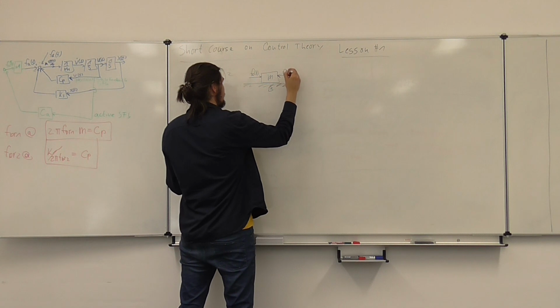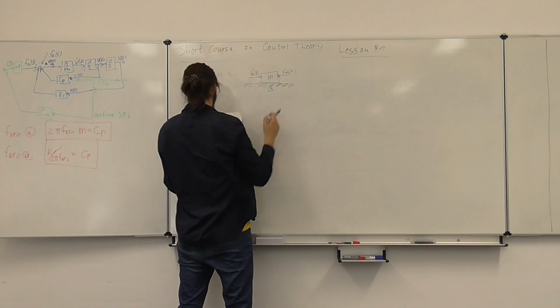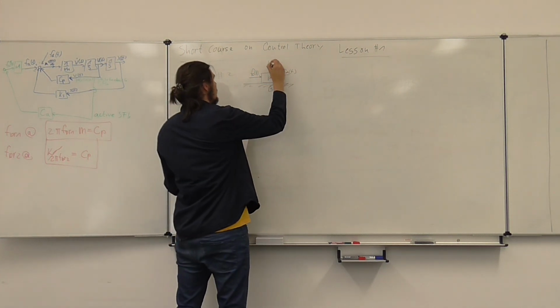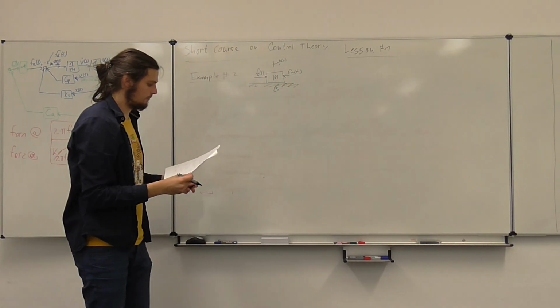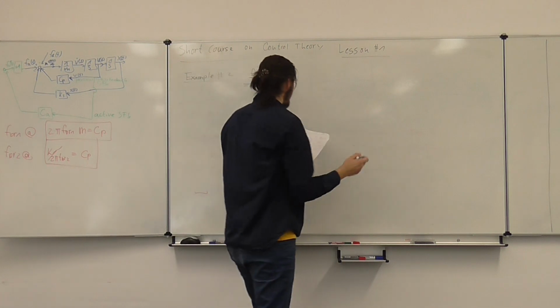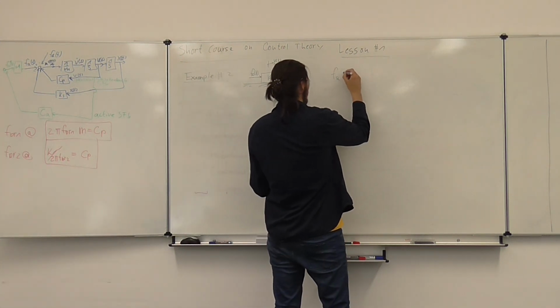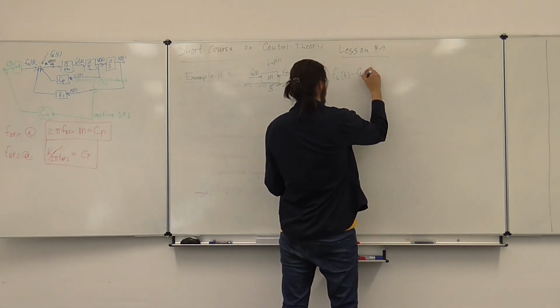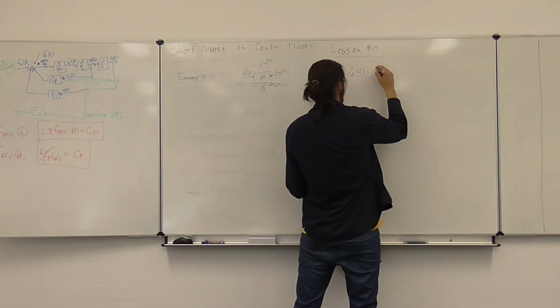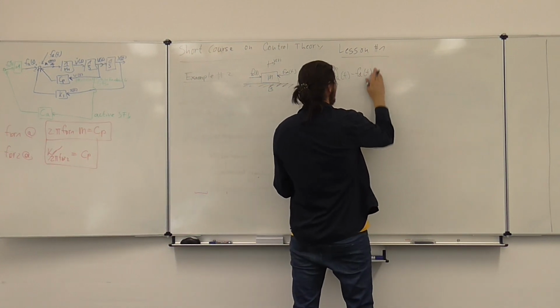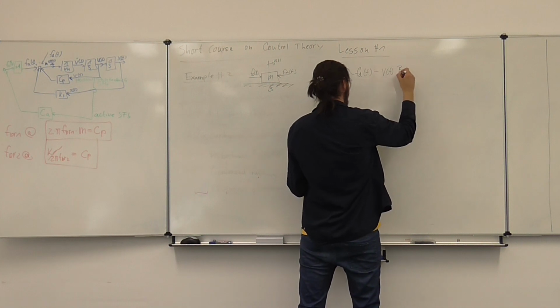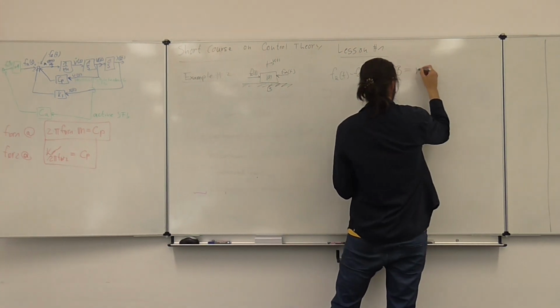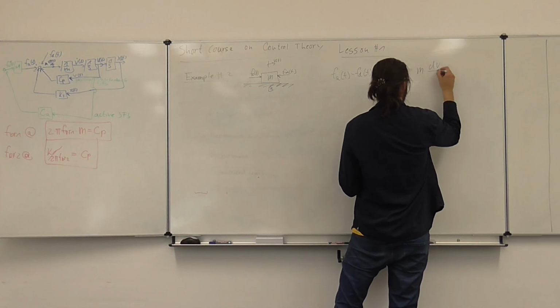We have our actuating force, we have a disturbance force. And we go into this direction. So the formula is very, very simple again. Fa of t minus Fd of t, minus the friction, minus v of t times b, equals m dv dt.